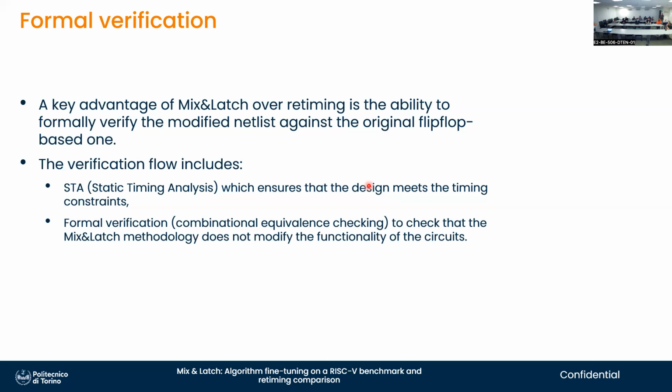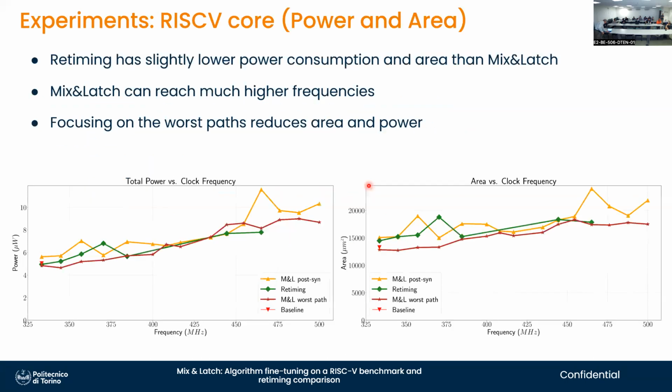Because I was expecting the power to be a little better. When you do the power estimation, do you do activity based? Yes, it is activity based, and actually the latches should reduce activity. No, because they let glitches propagate.